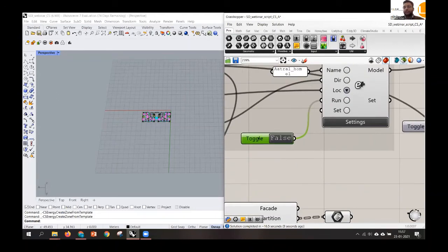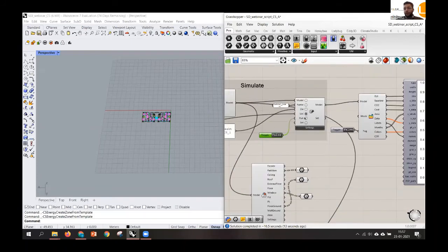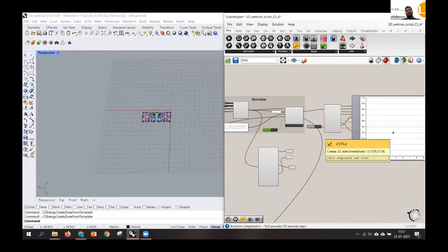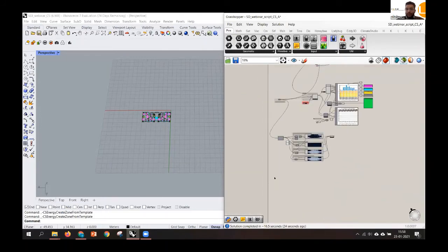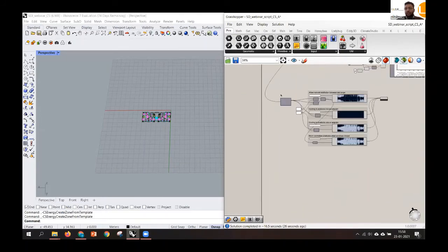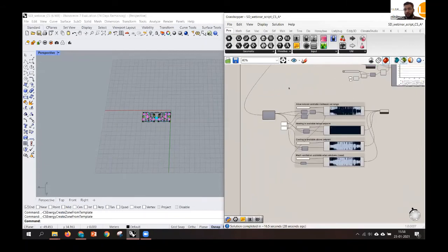So the simulation did not run. Here, when you turn this true, you will again see the reduction in the energy, and that is definitely because of the usage of free cooling. So ultimately, using this tab for your scheduling is a bit easy, because you don't have to manually put it in. It automatically makes the schedule for you.